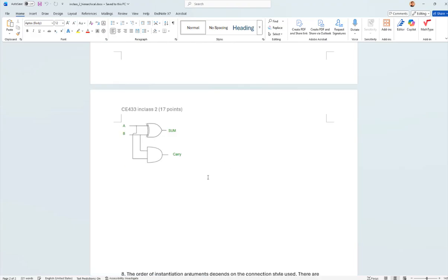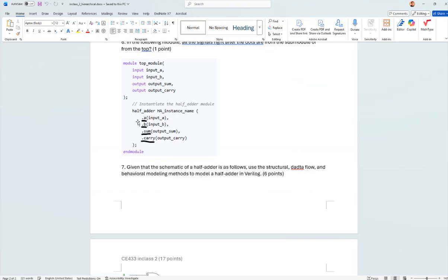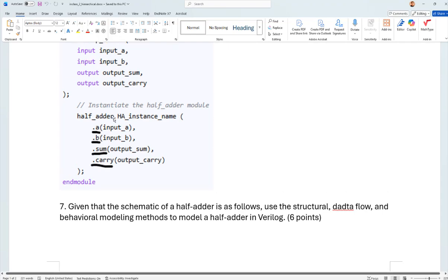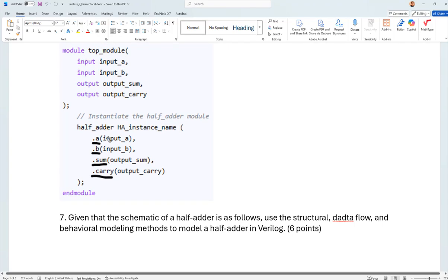Okay. So you see when they instantiate a sum module here, and they put the ports, dot the ports of the sum module and in parentheses the ports of the top. So this is the way they make a connection, right? Which means this port is connected to the top's port A, so on and so forth.